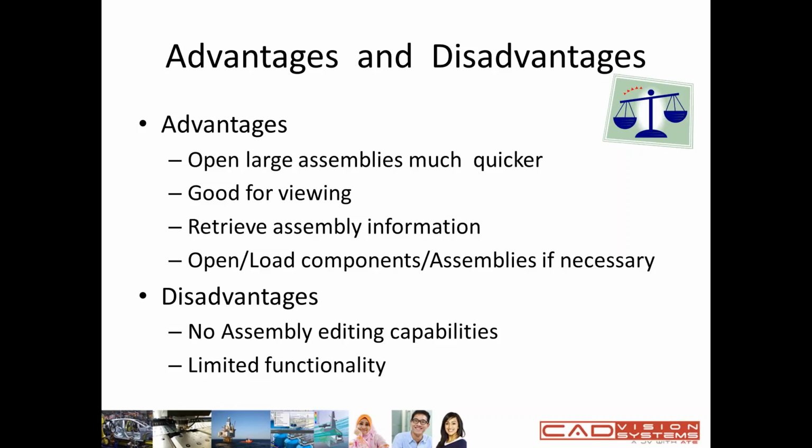Basically, I did a test on a model using Large Design Review, lightweight, Large Assembly Mode, and fully resolved. In fully resolved, it takes about 180 seconds to open one fully resolved component. In lightweight mode, it takes about 40 seconds to open.